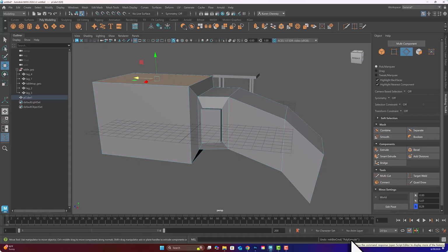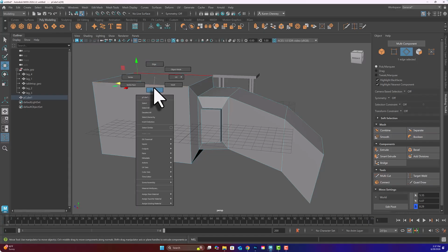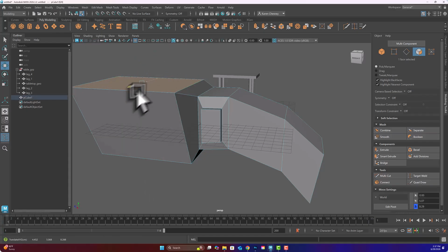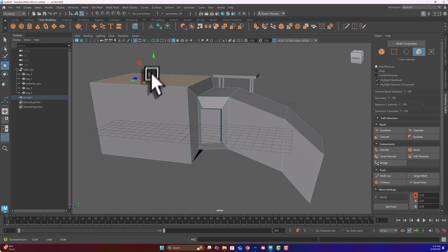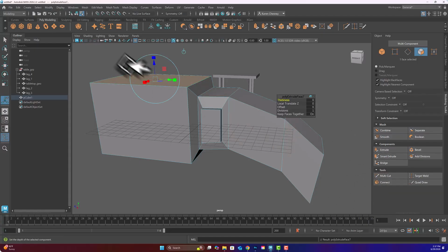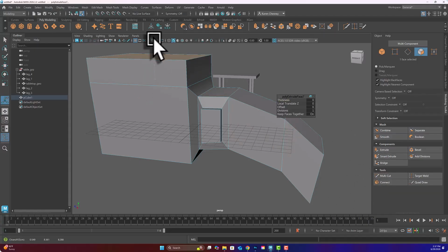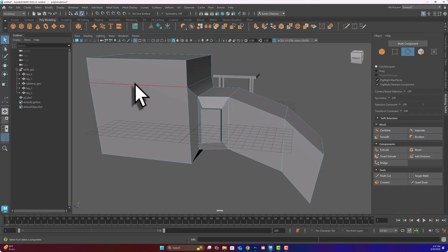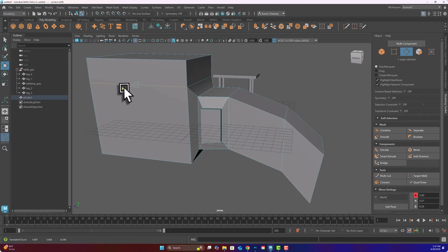Undo, poly extrude, that's the first one. And now we're back and this isn't messed up anymore. So if I grab this face and I move it, it's going to move the way we think it does. If I extrude it one time, like I'm supposed to, and then I grab this edge right here, this will pooch in the whole side like it's supposed to because there's not a ghost face there.